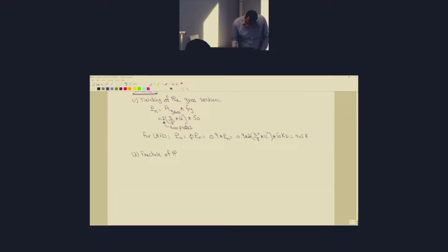Of the critical section. So how much is the net area of the 2 plates? You have two plates multiplied by, so the net area is the gross area minus the area of the holes, right? So it's 2 because we have 2 plates. The gross area is 3/8 of an inch multiplied by 12.